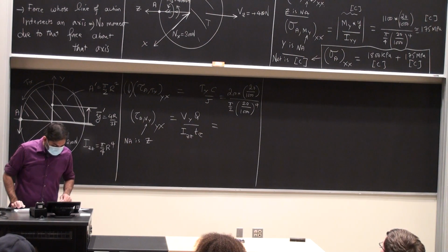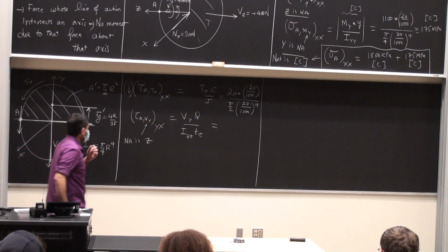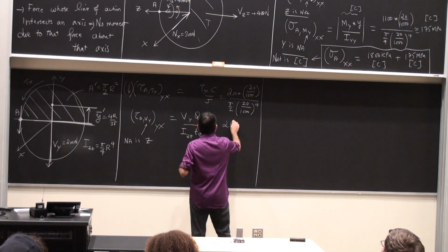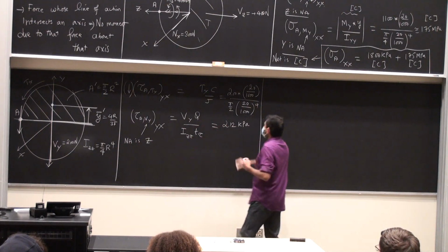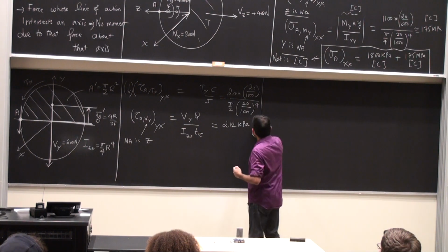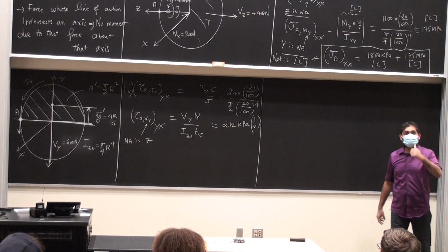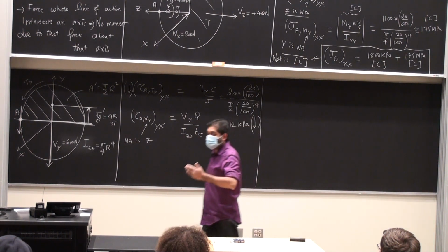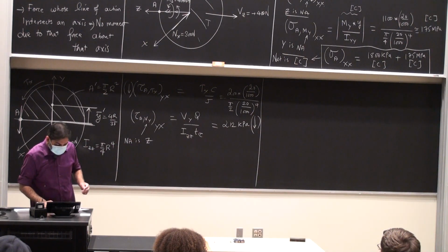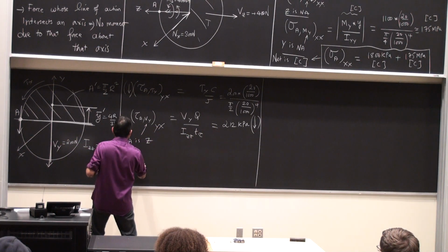So due to the shear force, it is going to be 212 kilopascals approximately. Okay, and this is going to be in the downward direction. Due to the torque, it is also going to be in the downward direction, but it's going to be an order of magnitude higher. It's around 15.9 megapascals.